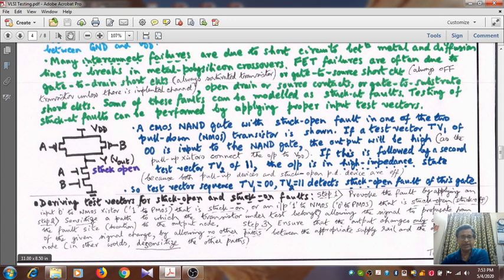Okay, right? So that first step is very important. Provoke the fault by exciting the opposite input that you suspect the device to suffer from. So for an NMOS transistor, if it suffers from a stuck on voltage, apply 0 voltage. If it suffers from stuck off voltage or stuck off defect, apply logic 1 to NMOS, and opposite voltage to the PMOS transistor.